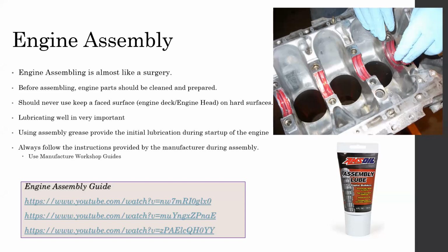But we have to remember that when the engine is working, all of these surfaces are getting pressurized engine oil. Until the engine starts to build oil pressure, in order to support these bearings and any other contacting surfaces, we can use assembly lube, also known as assembly grease. This is available in most shops. I'm not exactly sure how available it is in Sri Lanka, but it's possible to buy it there also. The reason it's not widely available is that most people are not using it.